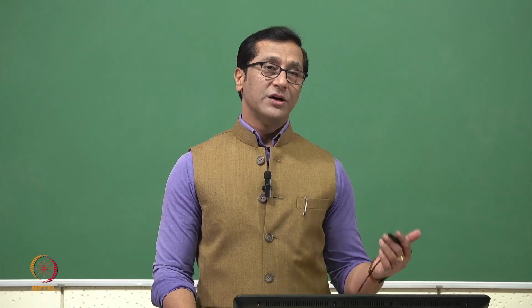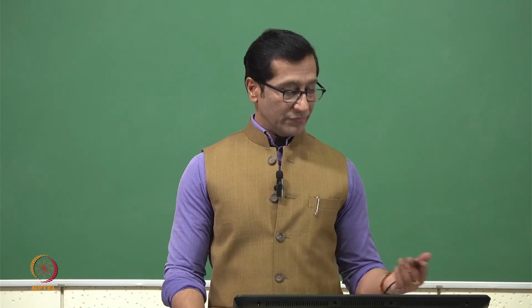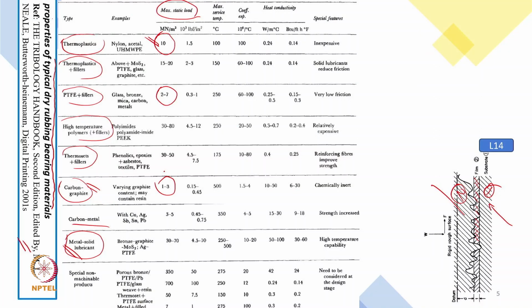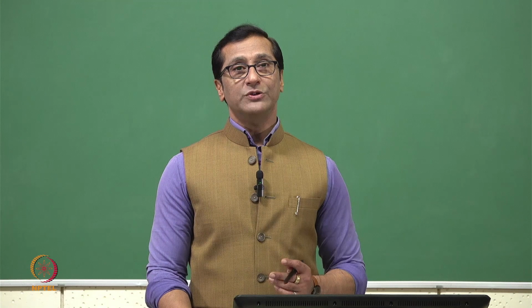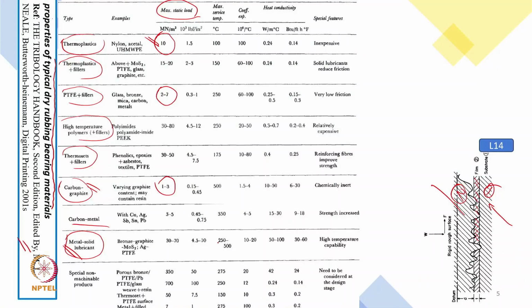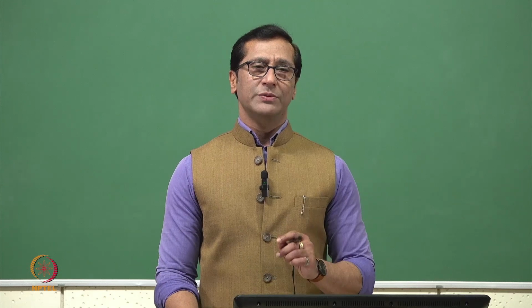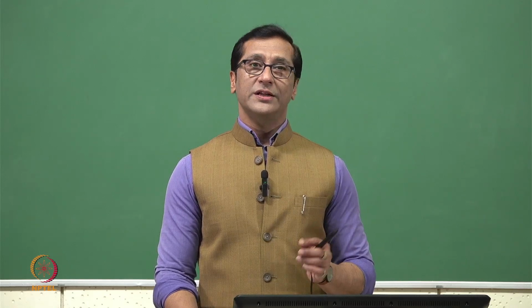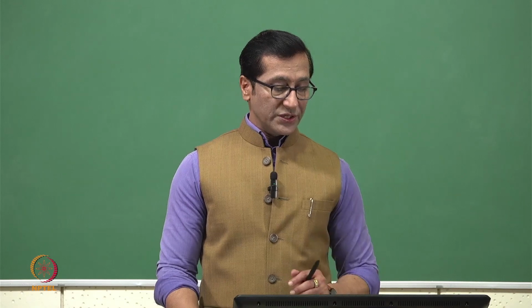If the load carrying capacity is an enormous requirement, then we cannot use PTFE even with the fillers. Even carbon graphite we cannot use as it is, because in one of the seals we use almost 30% antimony to improve the properties. So these are the important aspects. With carbon material, again, the strength is on the much lower side. Another one is the expansion coefficient. We say that we should have a high static limit and a low coefficient of expansion. If the coefficient of expansion is lesser, the chances of delamination, or separation of the solid lubricant layer, will be lesser. So those things are important.